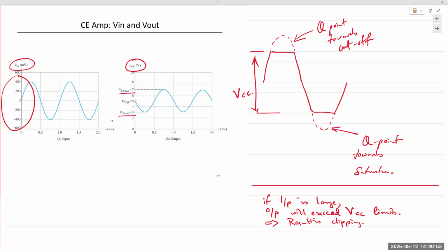And in real life, you'd experience a tearing sound coming from your speakers. So if you have ever turned the volume up in any of your audio systems beyond the capabilities of your amplifier or the speaker, then it will sound as if the speaker cone is tearing apart, right? I'm assuming you have at least on one occasion in all these years observed something like that. So what's happening is basically distortion or clipping of the waveform.